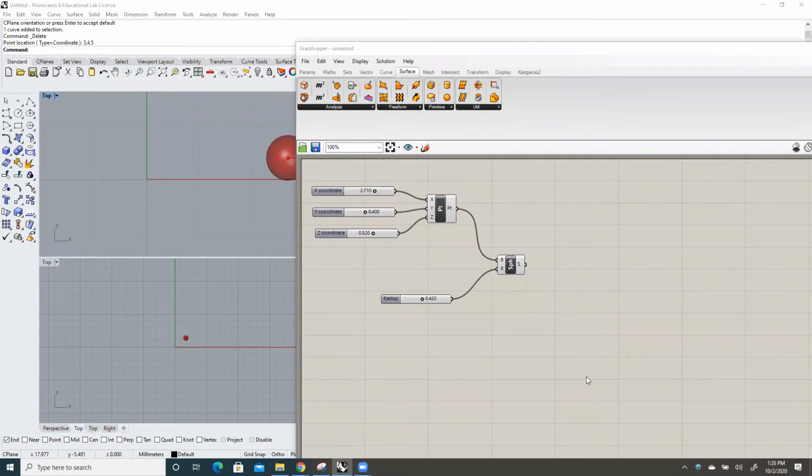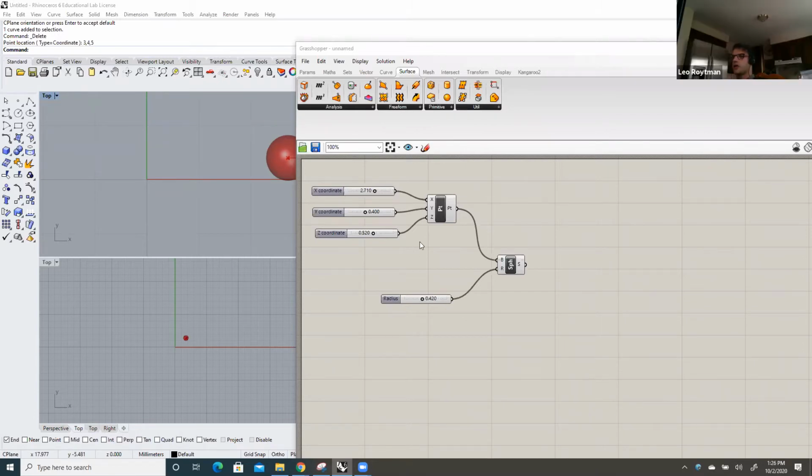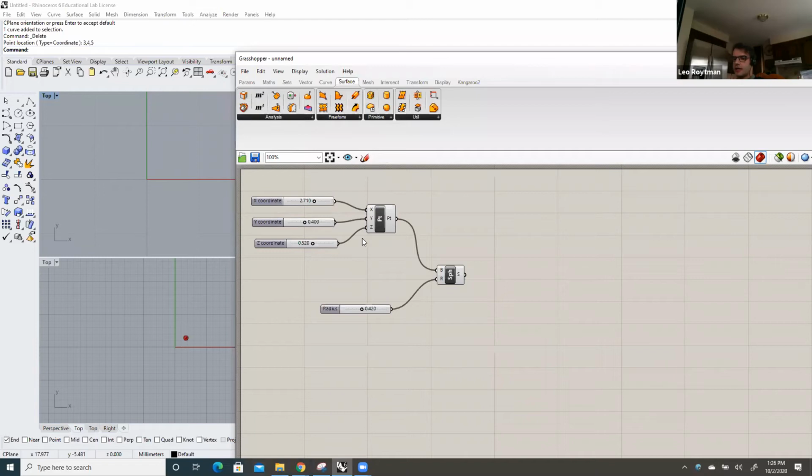If you accidentally connect two things that you don't want to connect, how do you unconnect them? Okay, to unconnect them, you hold control and follow the same path, and it will delete the connection.